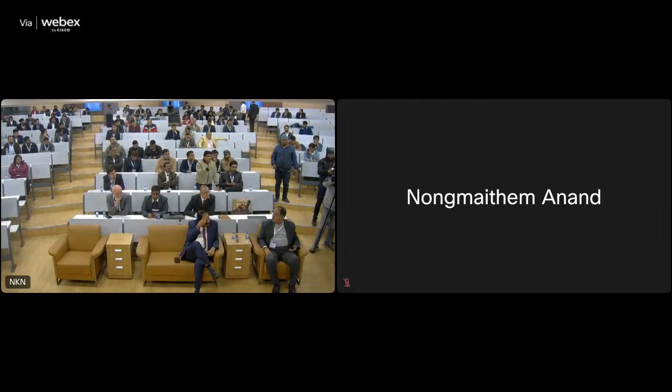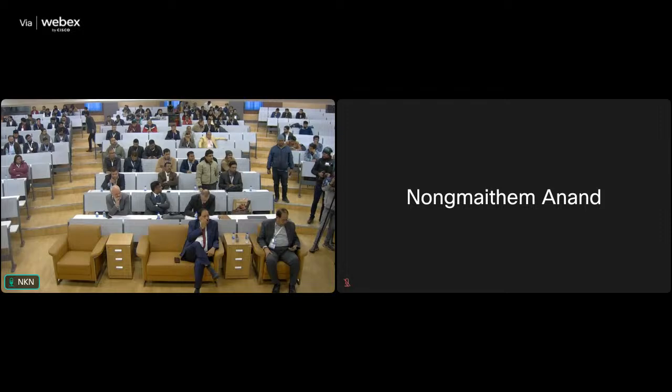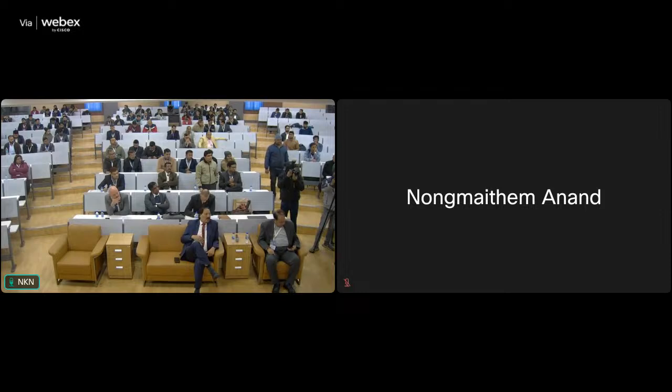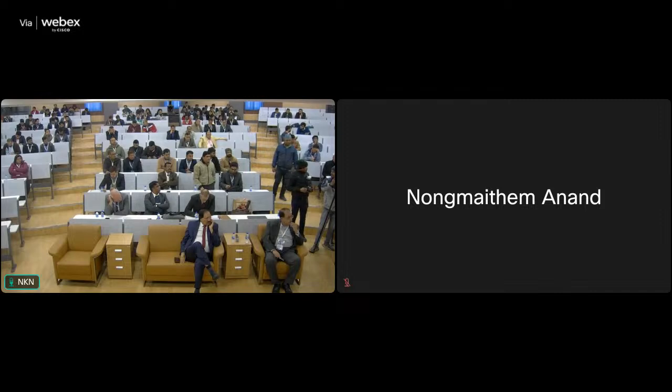No, that is not the thing. You see, the sequence is that just after the blasting, mucking and scaling, the first thing is the geologist will visit the face. He will map the geology. So your question is already solved. That means before sealing shotcrete, the geologist visits and maps all the joints and other things, because that will not be visible once covered by the sealing shotcrete. First is the visit of the geologist to the face to map the geology, and then sealing shotcrete. This is the step. And if you don't have that much standup time, then you should have either pre-injection, or forepoles, or pipe roofing.